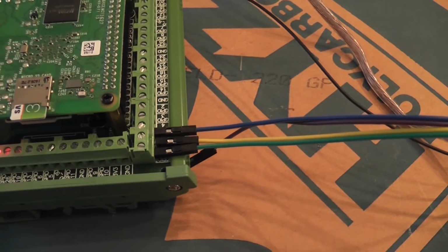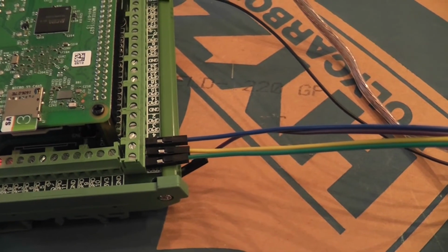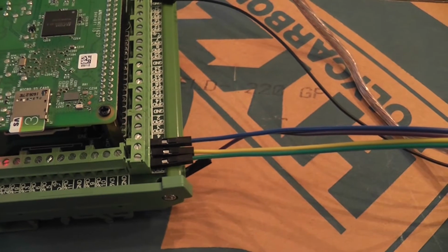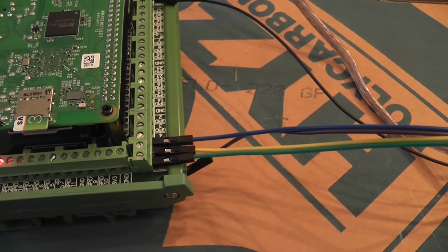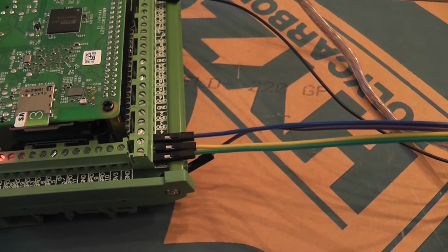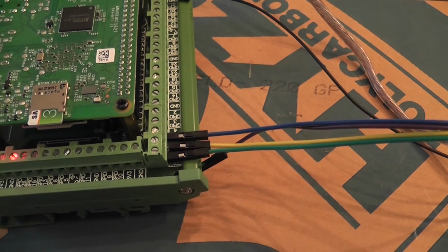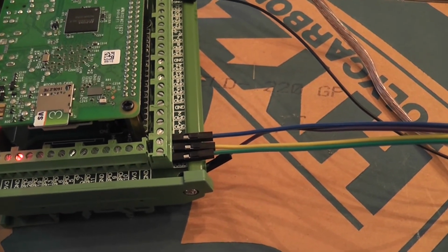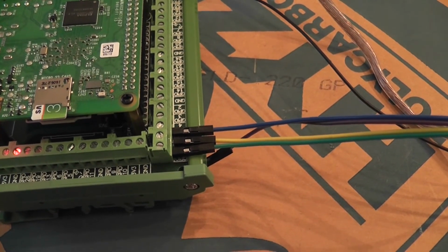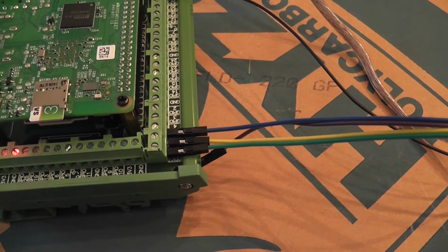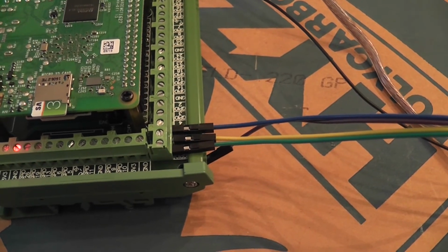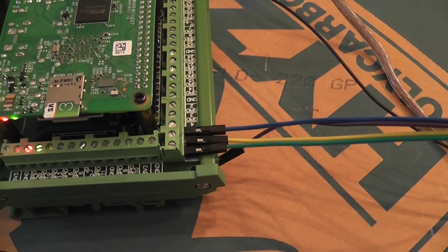The blue wire is using a pulse width modulated signal to adjust the voltage that goes to the rails, to the train, and to the train's motor ultimately. And then there's the yellow and the green wire, which control the direction. So if the yellow wire is a 1, it goes forward. If the green wire is a 1, it goes in reverse. If they're both 1s, something broke.